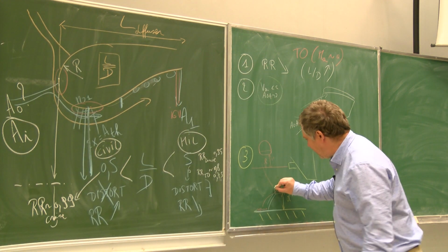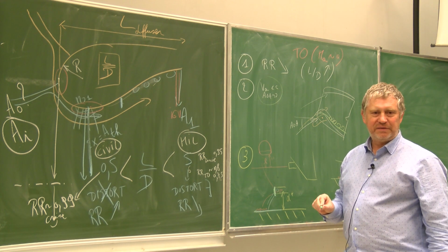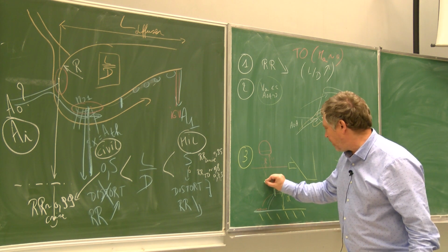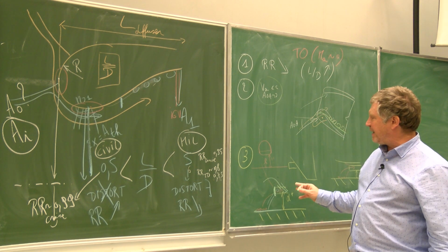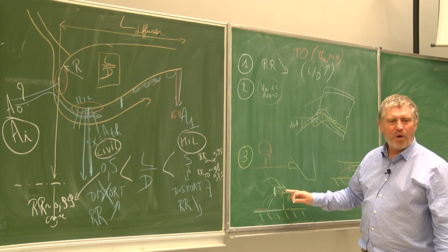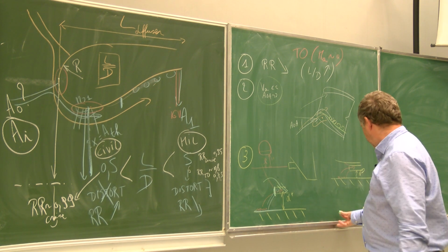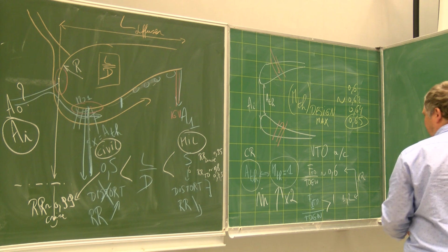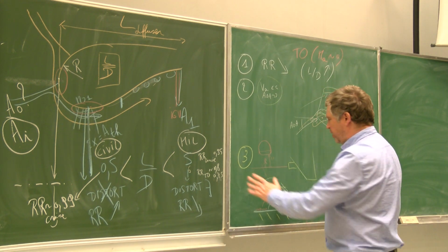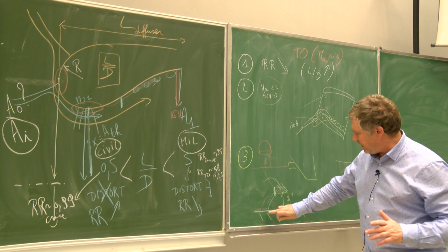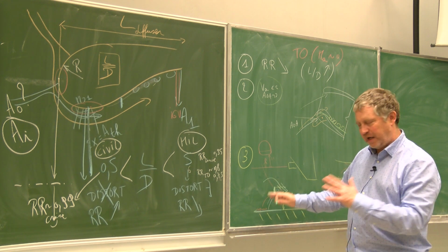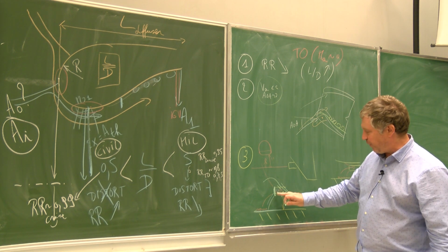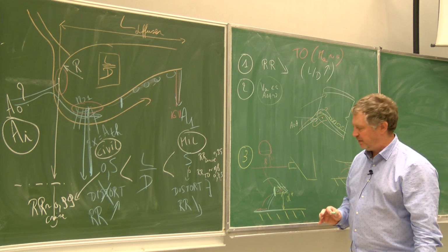They close the intake. They put a door here because it's too dangerous. And of course, at this moment, they need to open an extra door that is here. I'm mentioning that because it's not intended for vertical takeoff. It has nothing to do with what I have just explained there. It's just in order to protect the engine, you close the intake like this. The bolts or the tree branch, I don't know, cannot fly inside, and you open an intake there on the top. This is, for example, the case on the MiG-29.